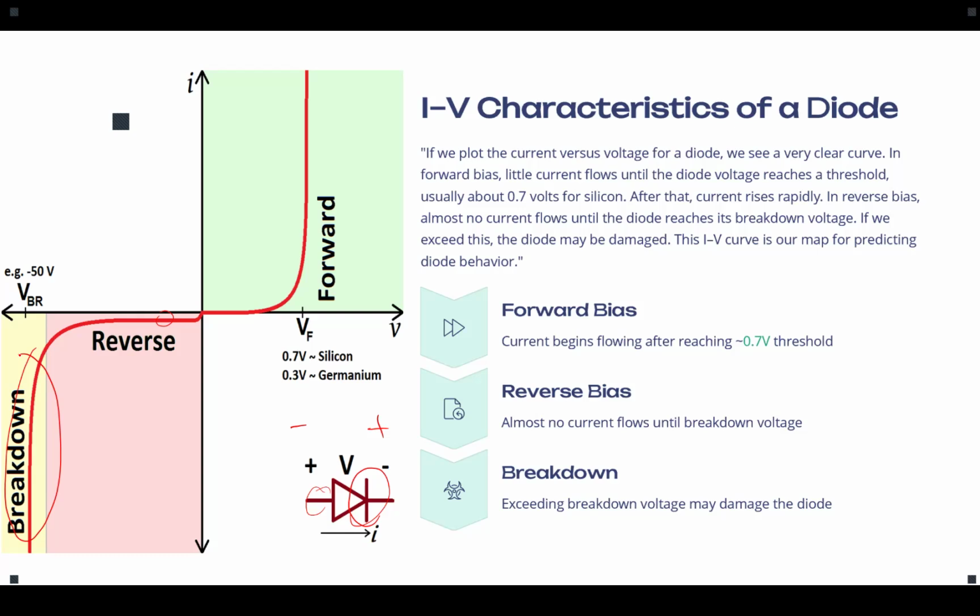The same goes for plus infinity. We have some limitation because it's a physical component. Now, if we reach a certain voltage, which is above the tolerance of that physical component, that component is going to burn out, which we call the breakdown. So at a certain voltage, we have a breakdown of our component. That means it's not a diode anymore.